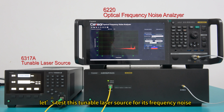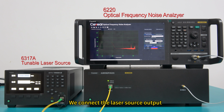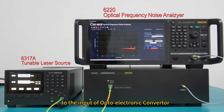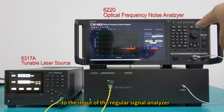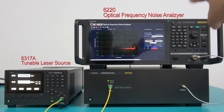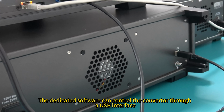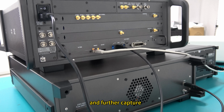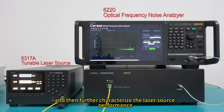Today, let's test this tunable laser source for its frequency noise. We connect the laser source output to the input of the optoelectronic converter. The converted RF signal is transmitted to the input of the regular signal analyzer. The dedicated software can control the converter through a USB interface and further capture and analyze the RF signal, and then further characterize the laser source performance.